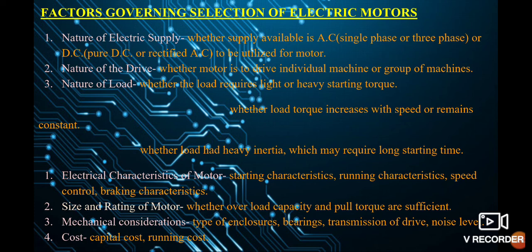Next one is the nature of the drive. Whether the motor is to drive an individual machine or a group of machines. The nature of the load. Whether the load requires a light or heavy starting torque, whether the load torque increases with speed or remains constant, and also whether the load has heavy inertia which may require a long starting time.